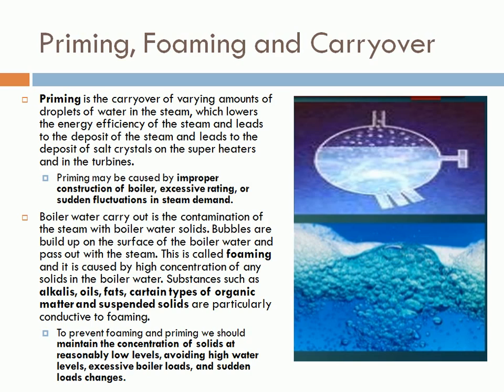It is harmful to the valves and pistons as the lubrication is washed away, and can be dangerous when water collects in the cylinders. Water is not compressible, and if trapped it may fracture the cylinder head or piston, right? The most frequent cause is running the locomotive with too high a water level in the boiler, and it is most likely when the regulator is opened sharply or steam demand is high.